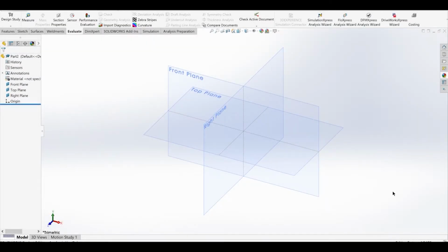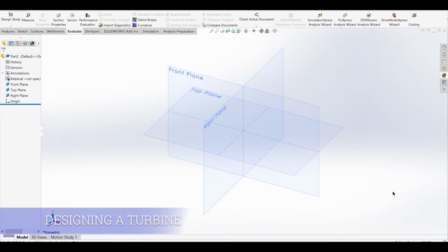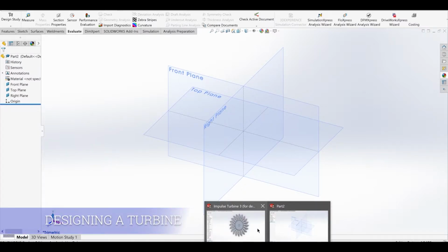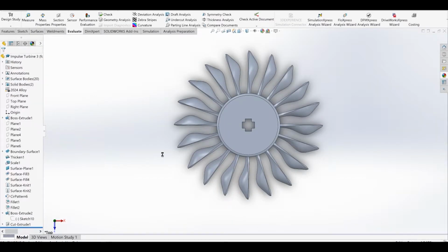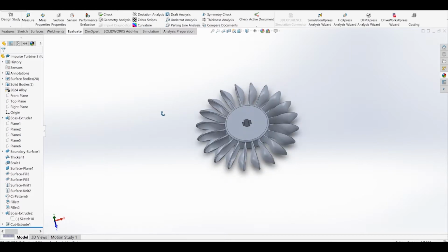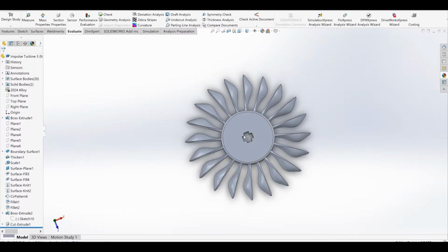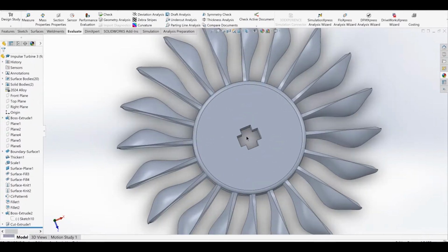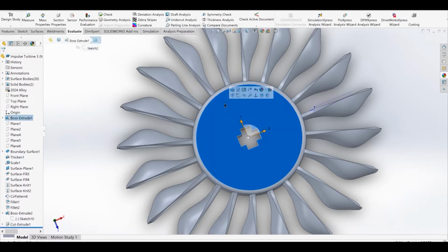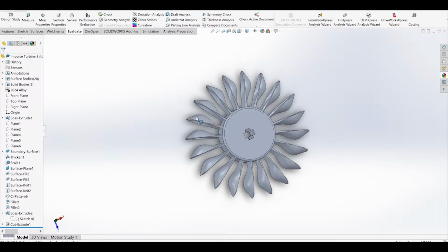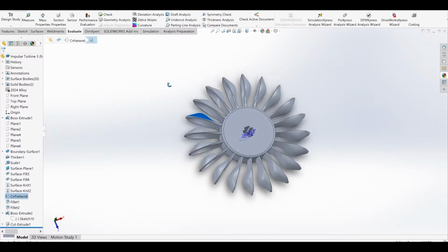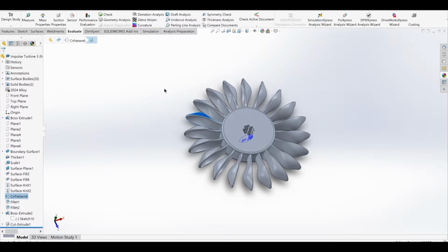Today you guys are going to be designing an impulse turbine, so I'm going to take a few minutes to show you how you can do that. In this other window I have up, there's a model of the demo turbine you guys will be looking at. As you can see, there's not too many parts to it. There's a cross section here of a hole to fit the rotating shaft into. Here we have the hub or the runner of the turbine. And then finally the blades or the buckets. These are what are going to catch the water that comes into the inlet that rotates the turbine.